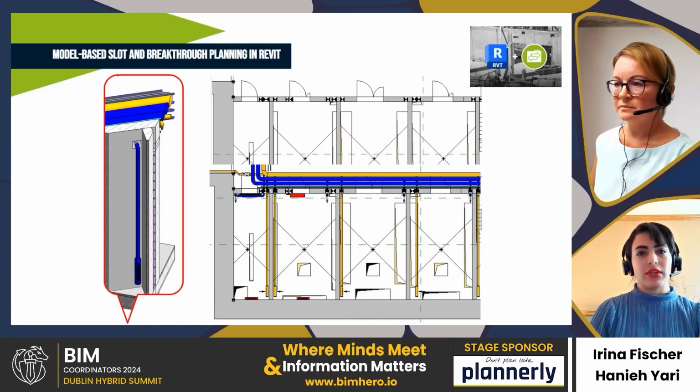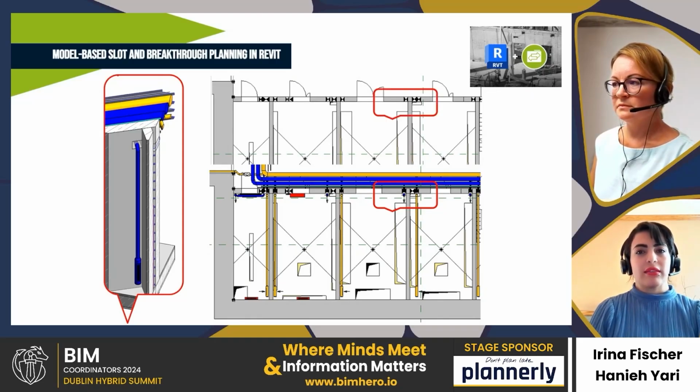When using Autodesk Revit in a BIM project, as a specialist planner, you model your own model. This results in multiple independently managed models, such as for architecture, MEP, or structural engineering. During project realization, these models are linked and related within Revit. Discipline-specific MEP elements such as ventilation, heating, plumbing, or electrical system can reference architectural elements like walls or ceilings.